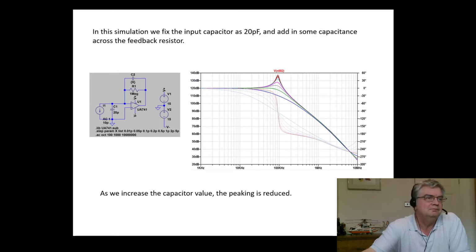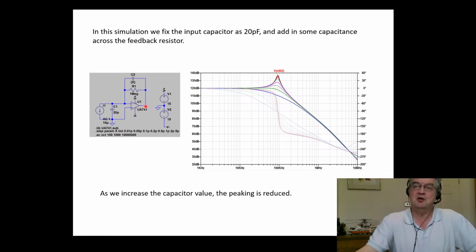Okay, so towards the end of the last lecture we were looking at this transimpedance amplifier, which was for amplifying current sources. Let me just get a pointer up. We were looking at this kind of circuit over here, where we were amplifying a current source through the virtual ground, and converting the current into a voltage through this resistance here, and that generated an output voltage at the op-amp. So the op-amp is maintaining its output voltage to keep 0 volts between these two inputs. So it's the virtual ground operation.